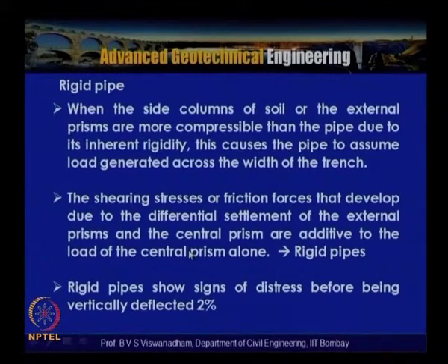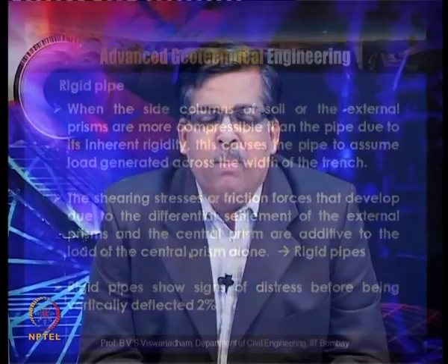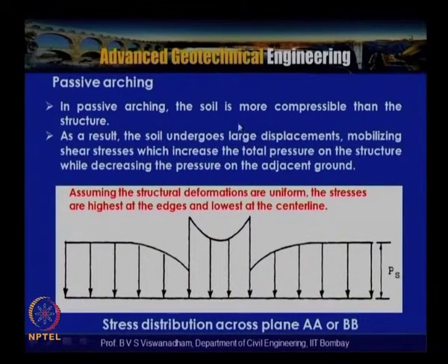So after having seen active arching and passive arching, we said that in case of passive arching, the soil is more compressible than the structure. In case of active arching, the structure is more compressible than the surrounding soil.